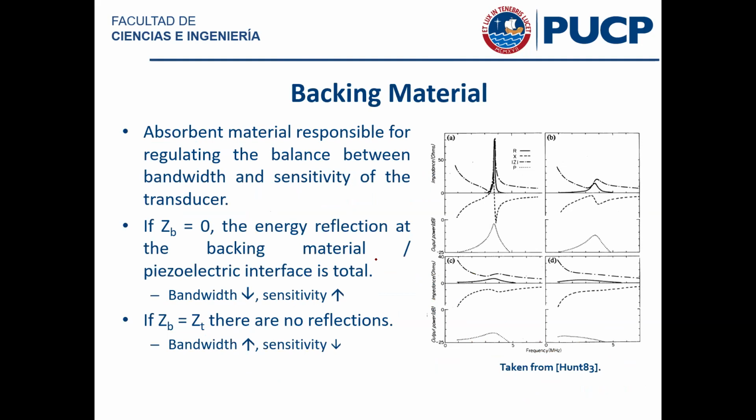Now, the thing about that is just really think about it, right? This means that technically speaking, the transducer is going to generate waves that have a very large amplitude for one particular frequency, and then away from that frequency, it's going to generate relatively weaker waves, right? That's the idea of resonance. You have a very large response for one frequency, and then for the other ones, you get really weak responses. And why does that happen?